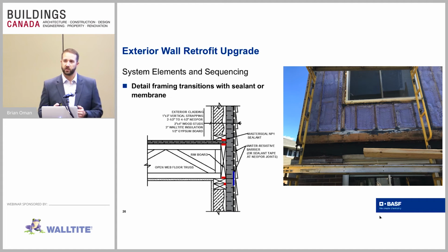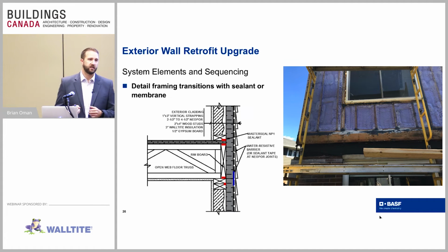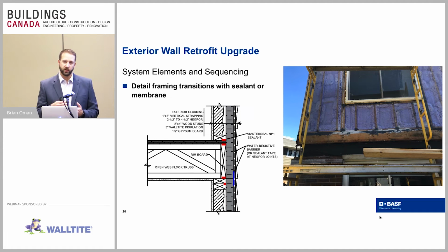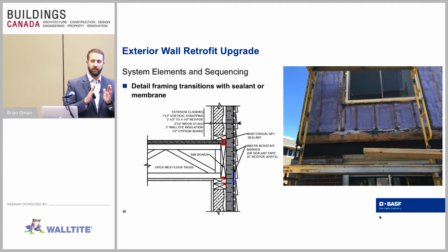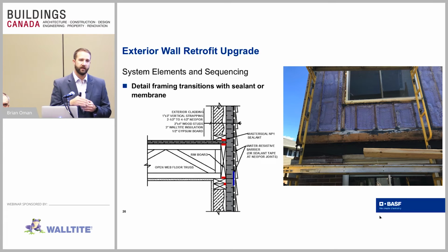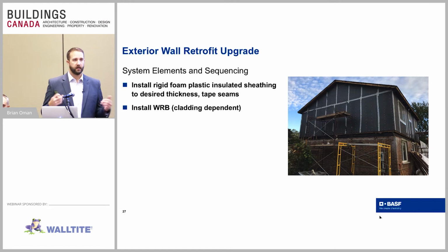So we're using, as Chris said, an elastomeric polyurethane sealant or an acoustical sealant to go through and detail these areas. We're going to make sure that all of these wood-to-wood connections, and that could be maybe 2 studs connecting, maybe it's plates connecting. It could also be, in this case, where our plate and our subfloor, or where our subfloor and our rim connect together. We want to detail those joints to make sure that we don't have any air or moisture penetrating through those points. Once the details have been done, now we can get our exterior sheathing put back on.